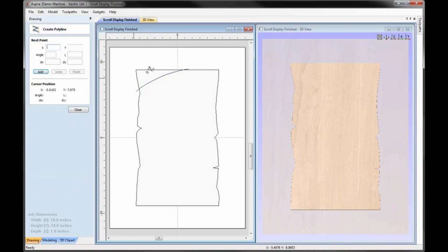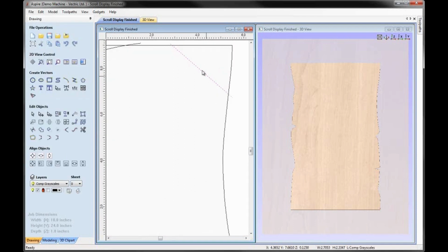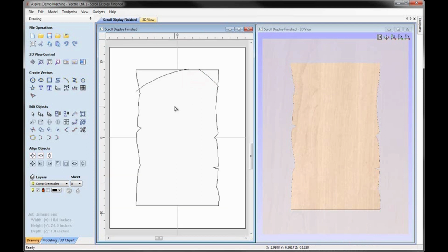Next I'm going to come back to the Draw Polyline tool. This time we're going to draw one across the corner here. Again, just going slightly past the edges. I can zoom in there, hit N on the keyboard, B for a Bezier span, drag those up. I'm not going to give that much curvature. Hit Escape, F on the keyboard to fit that.